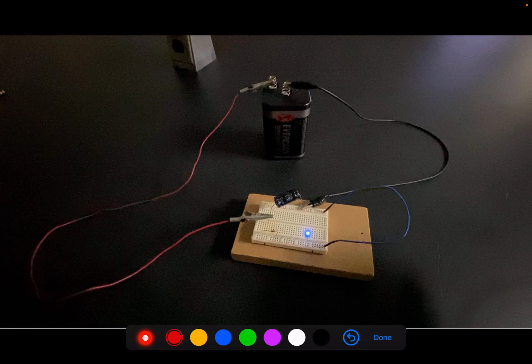When we look at these graphically, we would see our current dropping. It would have a y-intercept of the original current. And like I said, we can find that by doing the original voltage divided by resistance. The charge on the capacitor will have the same graph, and the original charge should be equal to the capacitor value times the original voltage.